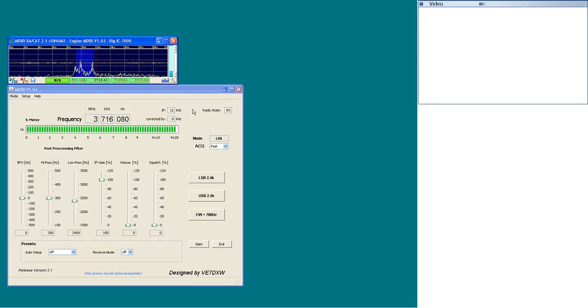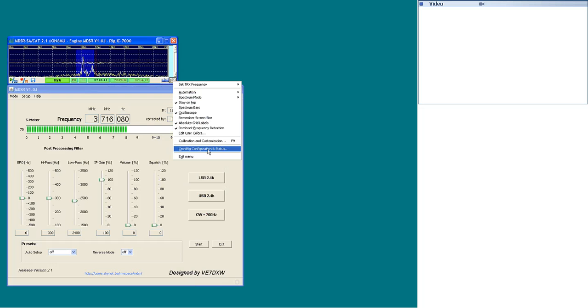How to set up OmniRig. OmniRig is the universal RS-232 translator, which has the capability to provide CAT control to 48 different transceivers. The setup is as simple as defining a COM port and a rig. Open the CAT Status Configure OmniRig window by selecting the wrench icon, and then OmniRig Configuration and Status.